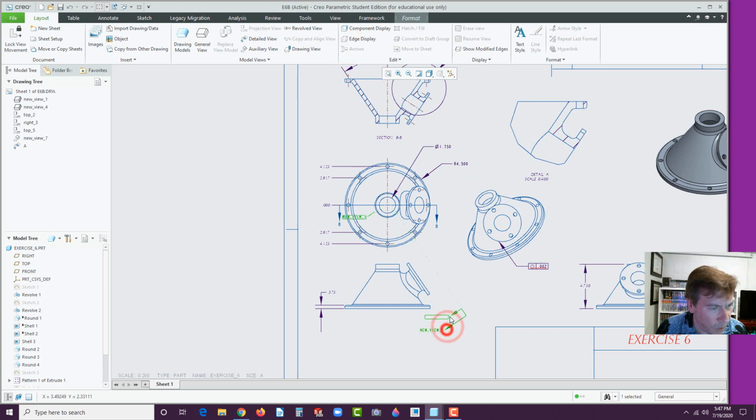Now where I worked, we didn't leave this name view on. Let's move this out here. And so what you can do, you could right click and hide arrow text. Now it's interesting, I clicked on this one and it hid the other one.